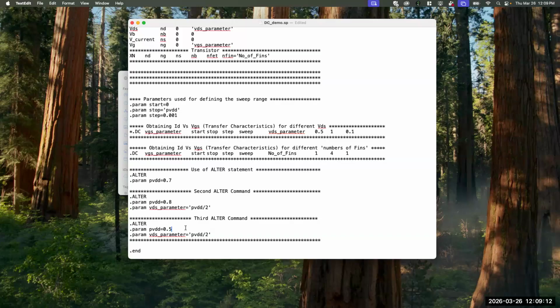How can I know that this transistor actually reached saturation? Because it is not as simple as VDS equals VGS minus VT, like the bulk transistors used to have, where whenever you cross that threshold, it saturates. No, that's the old story. So how do you know that this transistor is saturated? There are other conditions of saturation that FinFETs have to abide by. Turns out SPICE has a really interesting feature of assessing the modes of every transistor, and it generates a file that lists the mode of operation for every transistor.